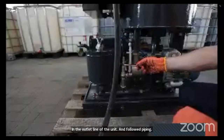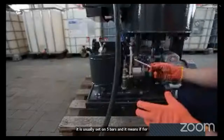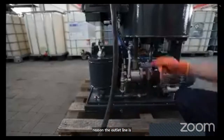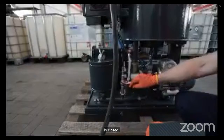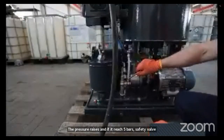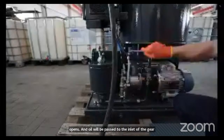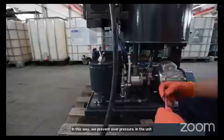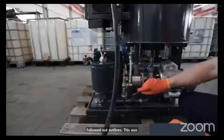It is usually set at 5 bars, and it means if for some reason the outlet line is closed, maybe some valve is closed, the pressure rises, and if it reaches 5 bars, the safety valve opens and oil will be passed to the inlet of the gear pump. In this way we prevent overpressure in the unit and followed outlet lines. This was about the first bypass, safety.